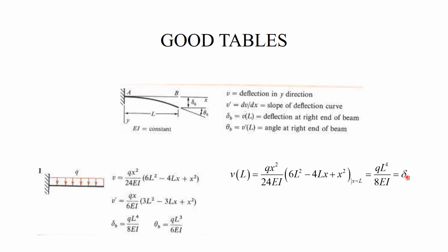I can do actually more. I can take V, differentiate it twice, and calculate the bending moment. And I get a quadratic function, which is consistent with the bending moment diagram, of course, and observe that at x equal to 0, the value of the bending moment is minus half QL squared, which could be easily established by drawing the free body diagram for the entire beam.